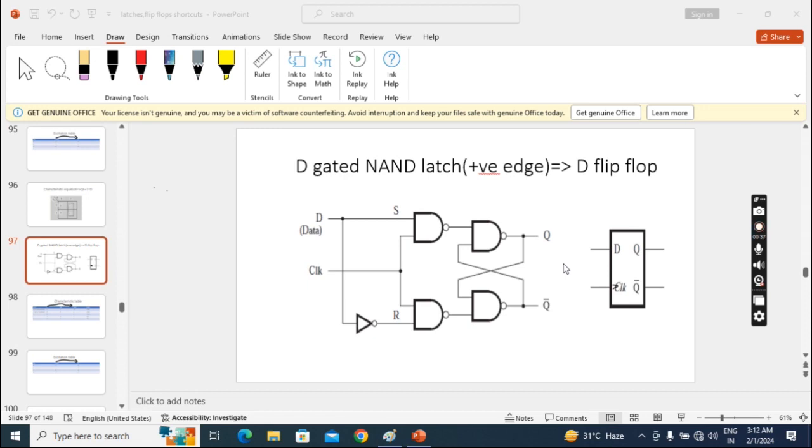In shift registers, we want to shift the same data, but after some delay, from right to left or left to right. So this D flip-flop is exclusively implemented for shift registers and for some counters also. Some counters means like the ring counter and Johnson counter. Those two counters are also called shift register counters. There also we use the D flip-flop.